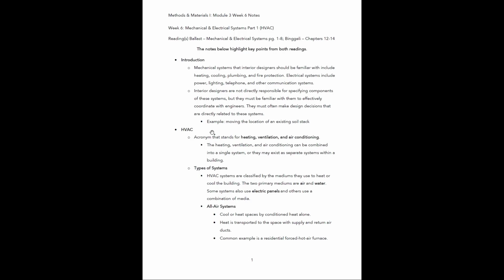All right, so for example, let's say we have a soil stack or some other piece of mechanical equipment, and it's existing in a building, and we might want to move it for one reason or another. We should have an understanding of what that soil stack is there for, why it is in the position it's in, so that we can understand if it is possible to be moved, and also who we would need to coordinate with to determine if it can be moved.